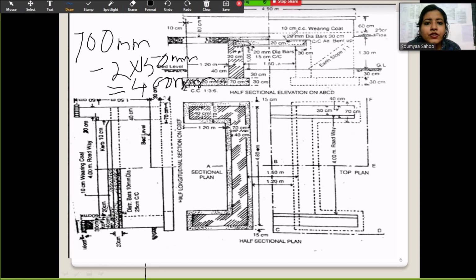In this sectional elevation you can also see the depth of the slab. Here the depth of the slab is 20 cm or 200 mm. Below the ground level and between the abutment, the portion is provided with stone pitching, and this stone pitching avoids the scouring due to flow of water. Okay, so with this background knowledge, we shall start step by step the detailed estimate of RCC slab culvert.